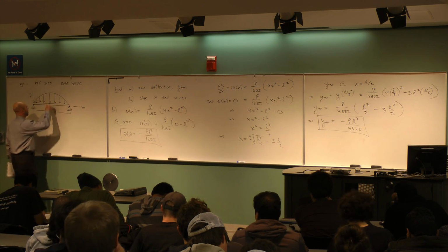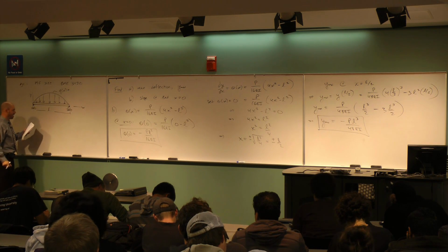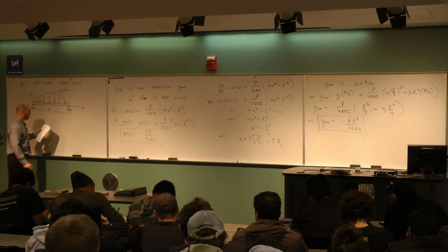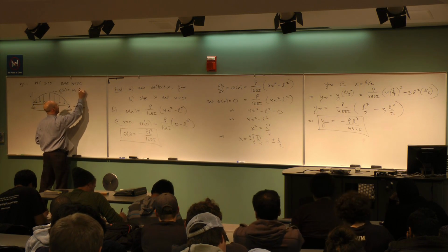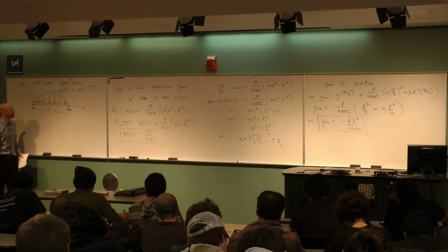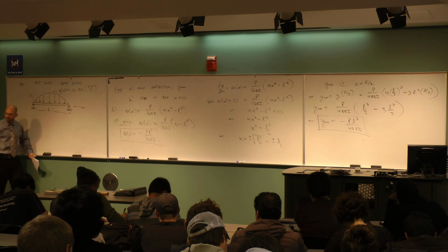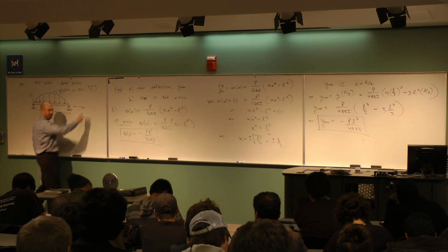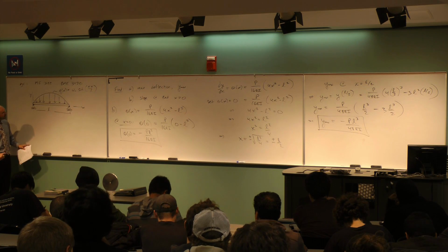So what would a sinusoidal load look like? It's a distributed load q of x. If the maximum value of that load is some number w naught, then I would argue that this equation needs to be w naught times the sine of pi x divided by L. So before you even solve this problem, I didn't even ask the question yet, can somebody give me a sanity check on this equation? How do I know there's not a typo here? Does that equation make sense?